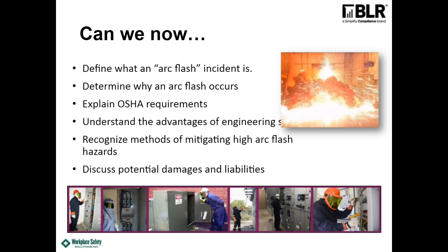And when you're talking about the main switchgear and stuff, you have a very good likelihood of, especially on the utility transformer side of the main disconnect, you have very long arc flash because you don't have any protection between you and the transformer, and it's going to take a long time to clear that fault, and that's why there's so much damage at that point.